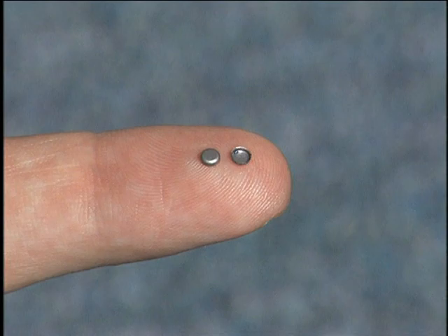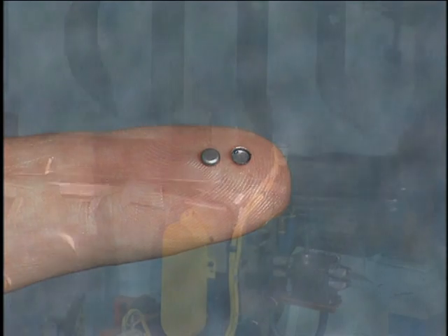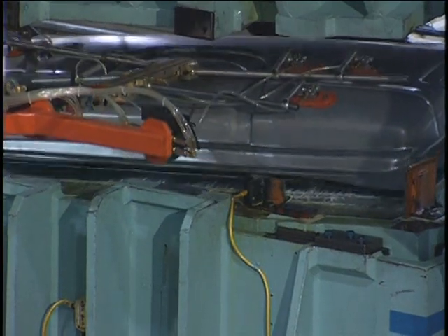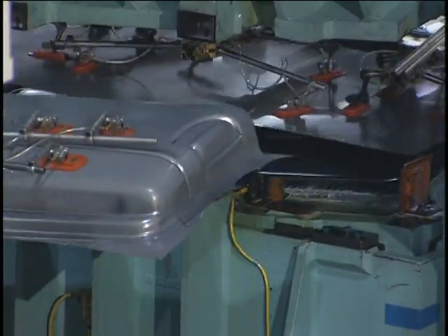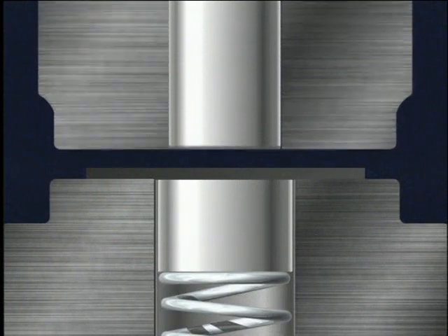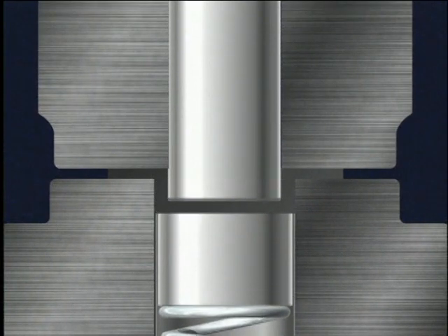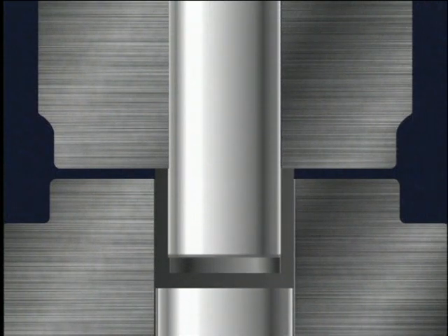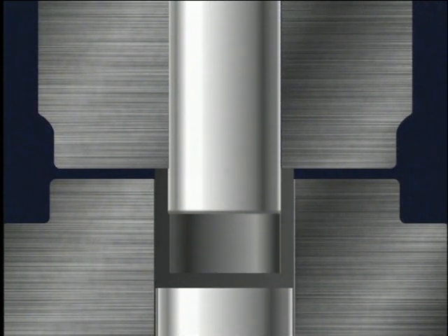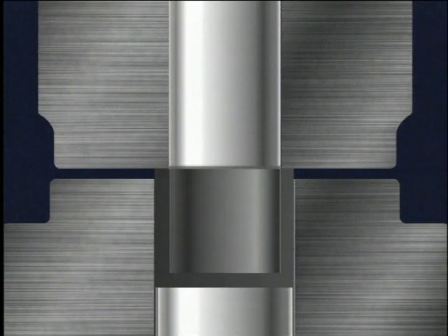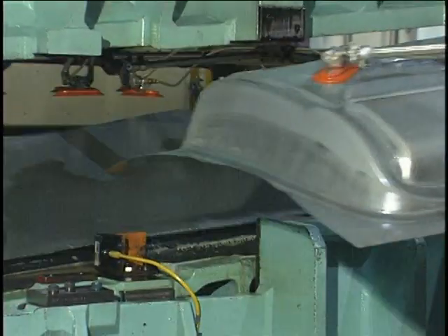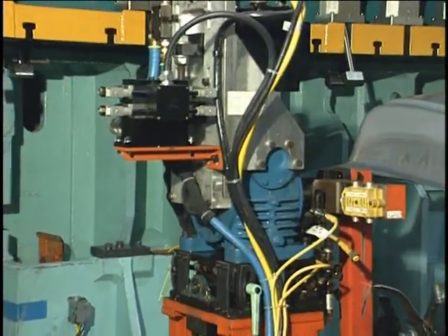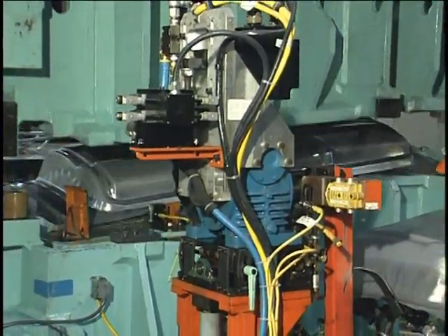Drawn parts may vary in size from small parts up to aircraft and automotive parts large enough to require mechanical handling equipment. For properly draw-formed parts, the force exerted by the punch must be great enough to draw the metal over the edge of the die opening and into the die. Additionally, the drawn metal must have a combination of strength and ductility to avoid rupture in the critical area where the metal conforms from the punch face to the punch sides.